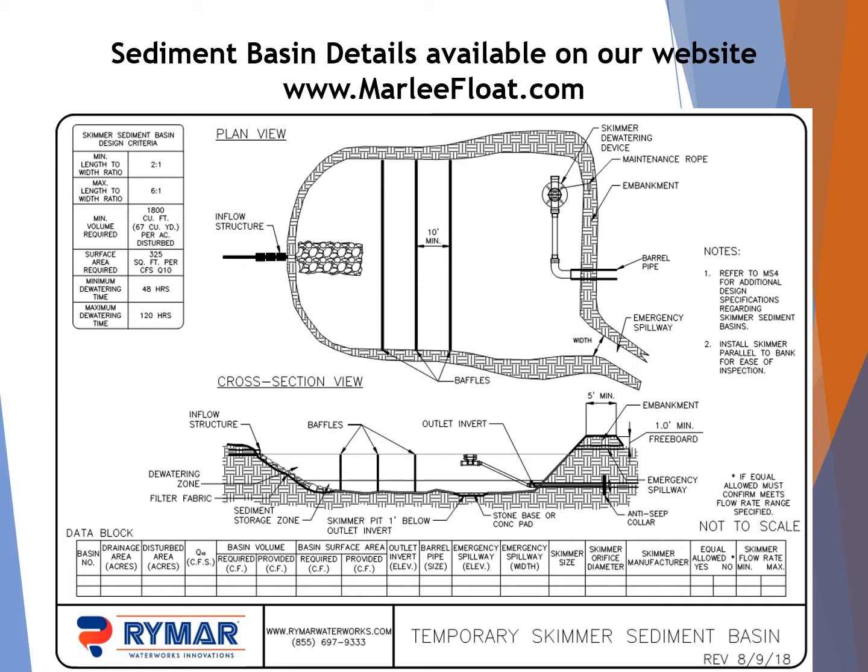We provide a chart for your standard sediment basin criteria that would apply to any sediment basins on the site. Note that we allow you to establish a minimum and maximum dewatering time range on the detail. We give you a data block where you can put in information for different basins on the site and expand